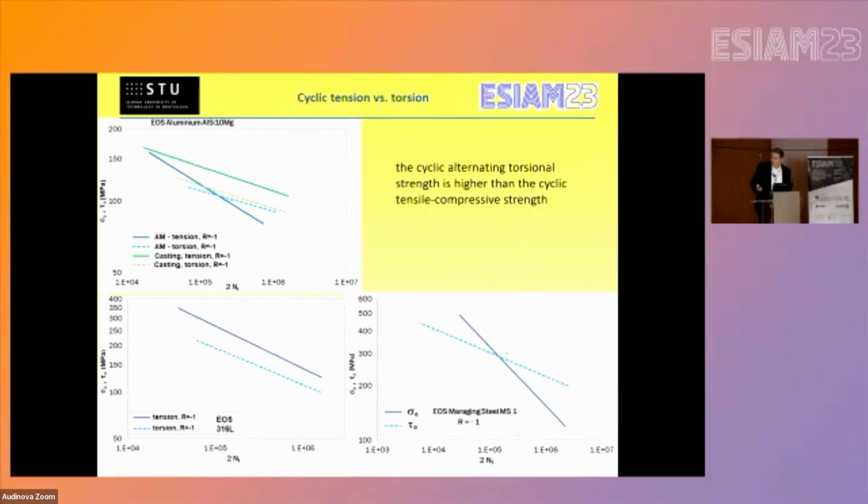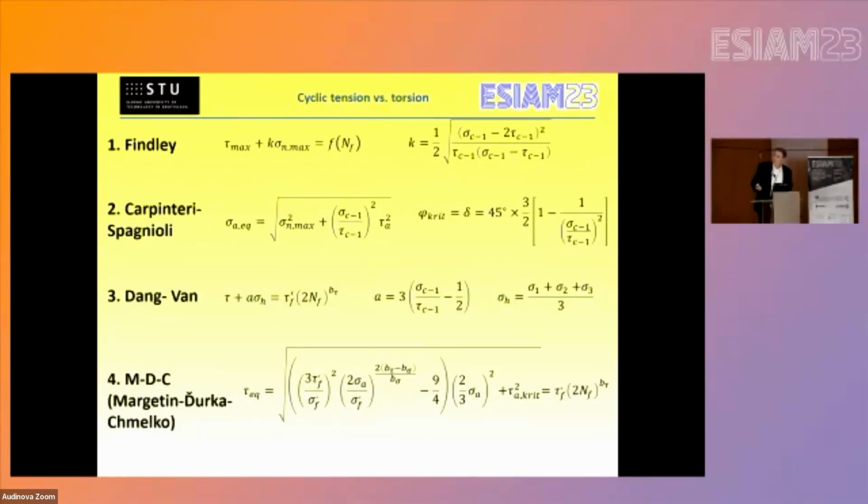Okay, so this multi-axial criterion does not function right with this ratio. From our university we have a different criterion in which we use the slope, not the fatigue limits, but the slope. And this slope functions well for this unusual behavior between tension and torsion.